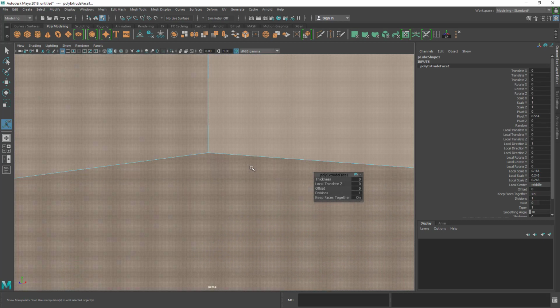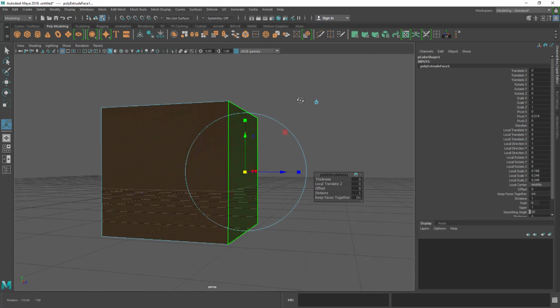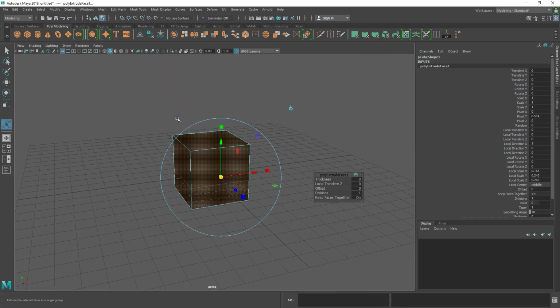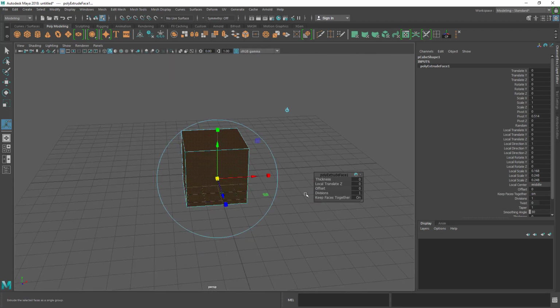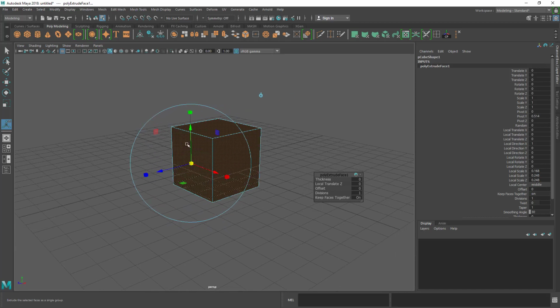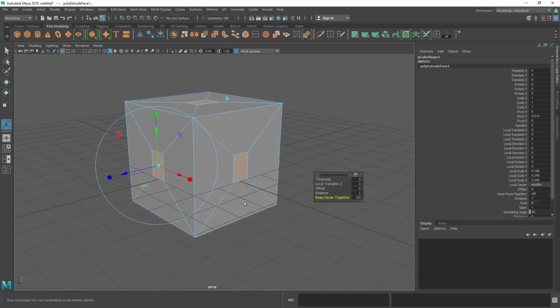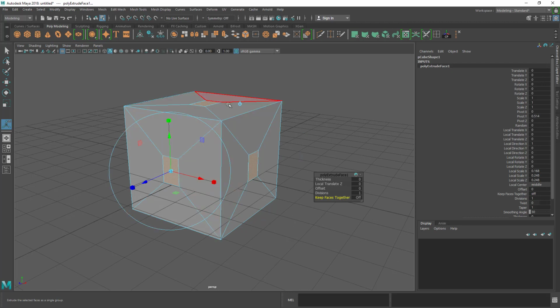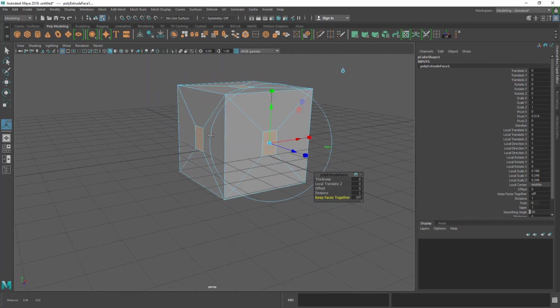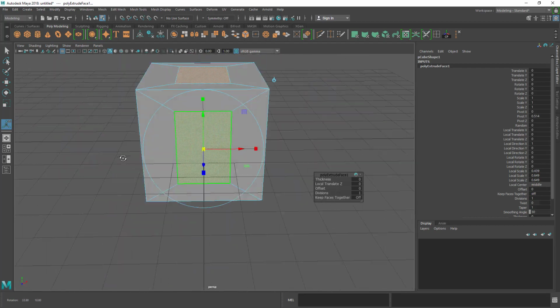Basically, because it is one shape and I just extrude the whole thing, it's thinking, well, we are one shape, so it doesn't make any sense. Why are you extruding all of us in one go? We just scale us up. So if we change this to faces off, faces together, so they're not connected anymore, they're their own separate identity, we can now manipulate every face